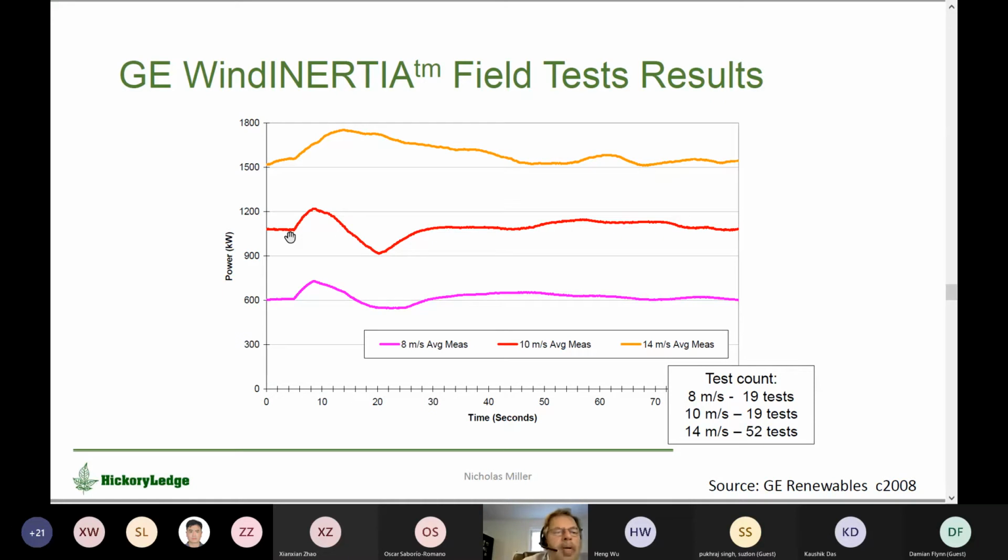Okay, so they're doing the best they can, and we get an increment of megawatts that is duration on the order of 8 to 10 seconds. That helps slow the decline of frequency and buys time for the primary frequency response to kick in. And then here we need to let the turbine recover. So this is the backlash.